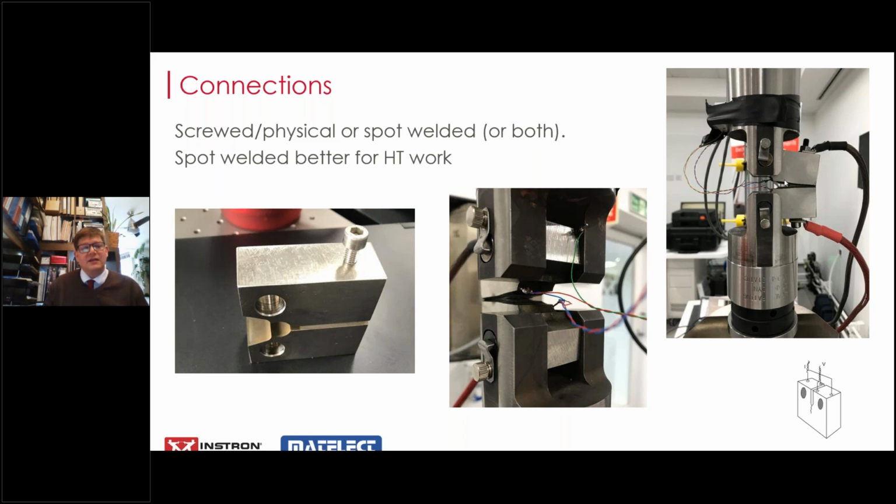We also recommend, where possible, particularly if it's a fatigue test, that you independently monitor the crack with either beach marks or something like that, or heat tinting, depending on your particular application. And then when you know those values, you generate your own calibration curve for your particular geometry which you are using. This is the way to get the best possible methodology.